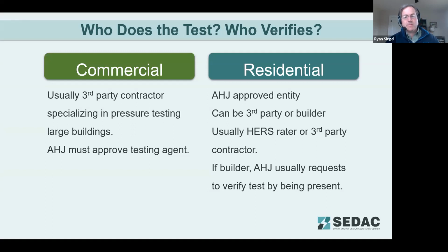So with that, let's touch on another poll here. Check and see if we've covered what we were looking to cover. So the first question is, what is the present Illinois air leakage limit for the building envelope? 0.4 CFM, 0.6, or 0.8 CFM per square foot for commercial buildings? And then for commercial buildings, what is the testing pressure? 0 pascals, 25, 50, or 75?